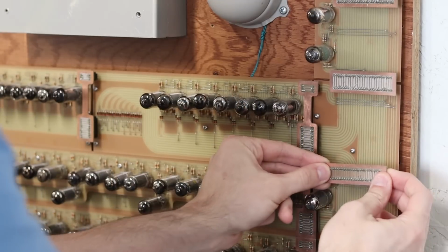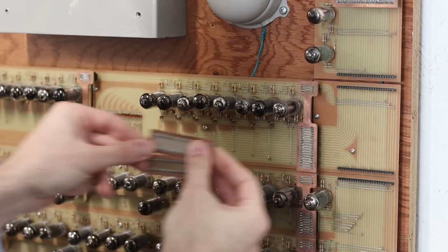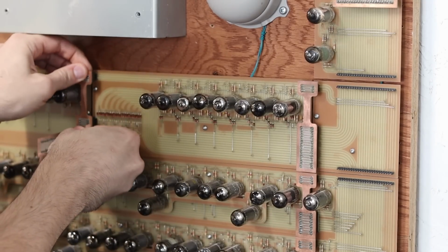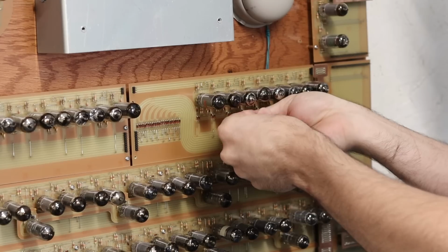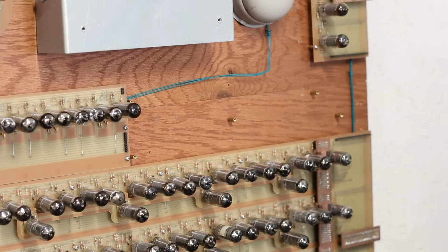And interestingly, it means that the scratch register was probably holding the correct answer to our math problem. We just had garbled output coming out because it's only the output register that's being affected here. The fault is on this big board right here, but in order to fix it, I'm going to have to connect a bodge to the board next to it. So I'll pull all the connectors off, remove the mounting screws, and then pull them off as a single unit.